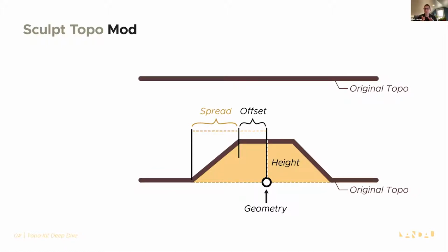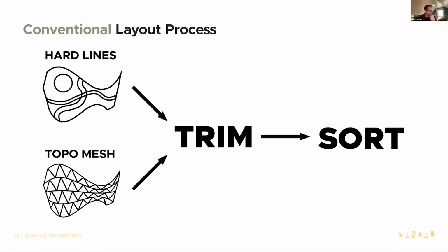But in a way, it allows you to push and pull the existing topography as it is, rather than having to define something in 3D space first and then grade away from that. Each of these tools, the grade and sculpt, have different applications, and we'll get into that.